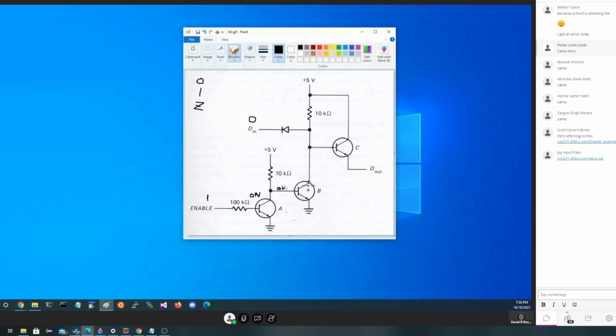Which says what about this transistor? It would be off. Right, we can't get anything from 0 to ground, so it's basically as though that line is cut. This stuff doesn't affect the circuit any longer if this is a 1. And that's going to be true if this is a 0 or a 1, it won't matter. So if both are enable cases, we know what these transistors are doing. So we're going to put a 0 here.